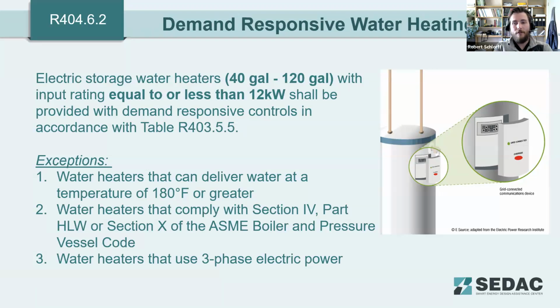Otherwise, if you have an electric storage water heater within the ranges and input ratings there, it does need to have demand response controls within it, whether or not those controls are being used or you're taking part in a demand response program, they need to have the controls there.